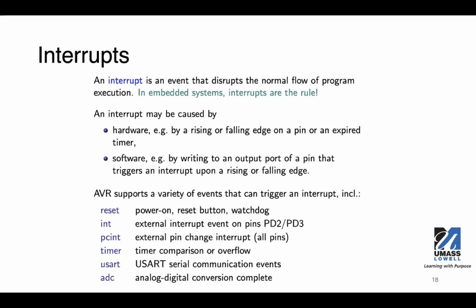An interrupt may be caused by hardware, for example, by a rising or falling edge on a pin or an expired timer. An interrupt can also come from software. You can write to an output port of a pin that triggers the interrupt option upon a rising or falling edge. And we'll see an example of that.